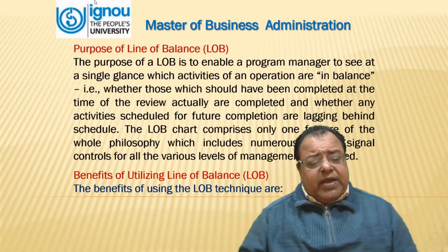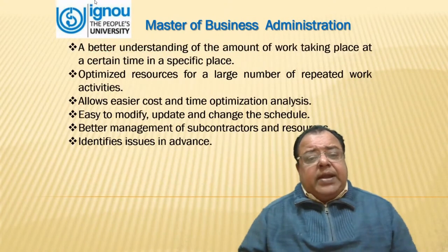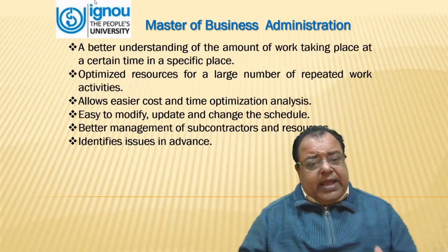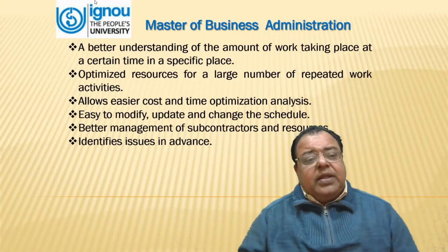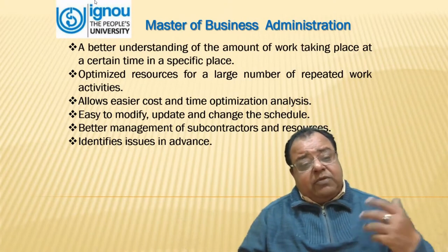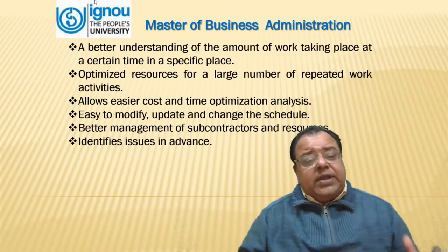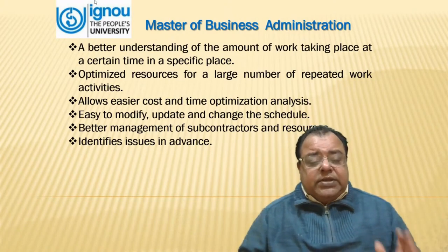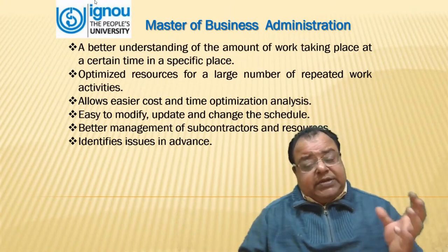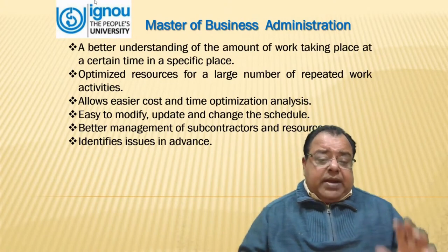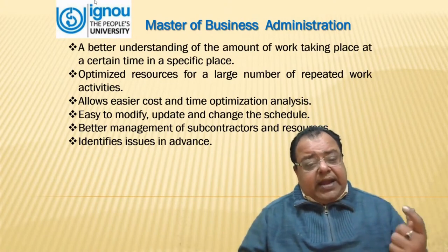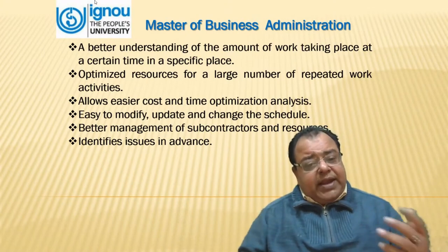What are the benefits of LOB? A better understanding of the amount of work taking place at a certain time in a specific place. Optimized resources for a large number of repeated work activities. It allows easier cost and time optimization analysis, is easy to modify, update, and change the schedule, gives better management of subcontractors and resources, and identifies issues in advance.